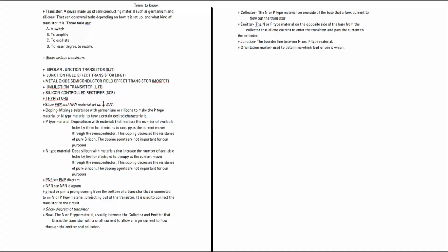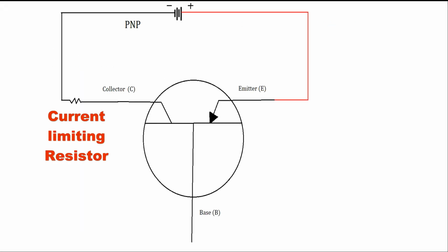It's called thermal runaway. To prevent thermal runaway, you install a limiting resistor at the collector of the transistor to put the brakes on the transistor, to slow it down, to limit that so it doesn't burn up. If you don't have that resistor, you will destroy the transistor.